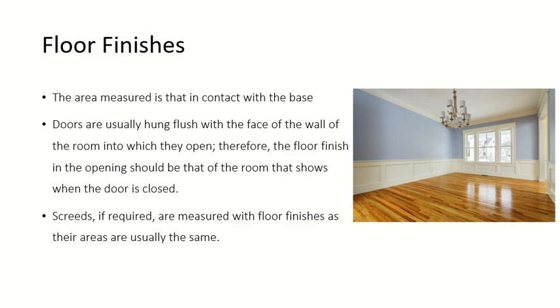The floor finishes are measured till the base of the wall. All floor finishes are measured till the base of the wall. We do not deduct anything for the doors, because doors usually open till the wall, right? So anybody who enters the wall will step on the floor itself. So there is no deduction done for the area which is under the door.